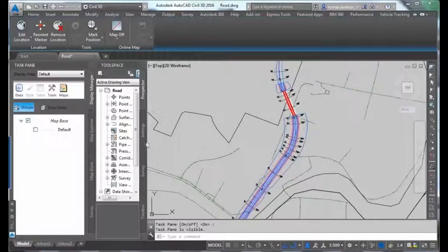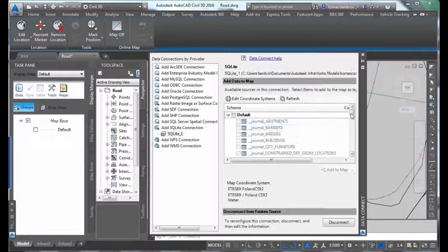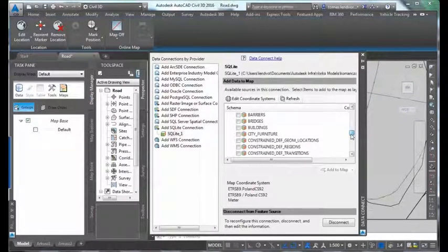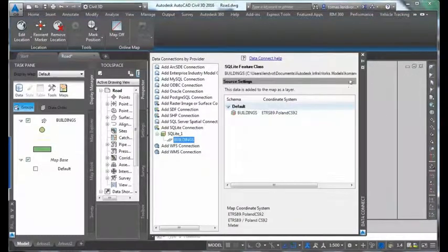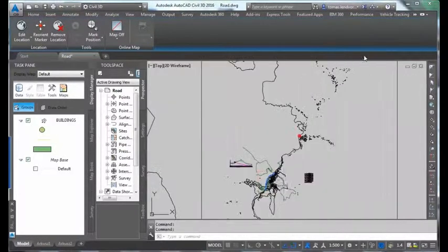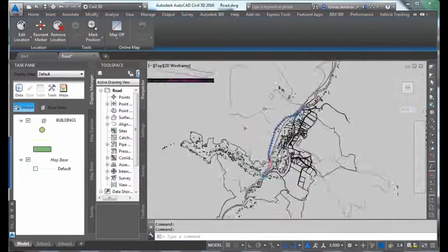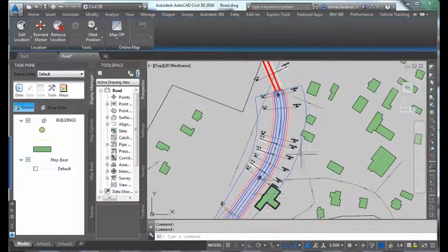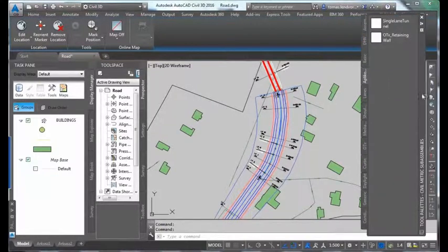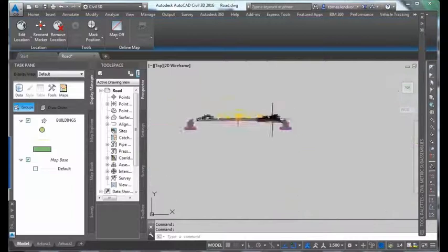And have a look what we can do. Now I'm bringing the data from GIS again, from InfraWorks. I'm bringing buildings because I made a road and then I realized, oops, where are my buildings? So I'm bringing them in. I just forgot it. It's obviously possible. And now I realize that my design is not the best one, because you can see that my fill, or my profile, is too high, so I would have to destroy several buildings, which is not very nice.